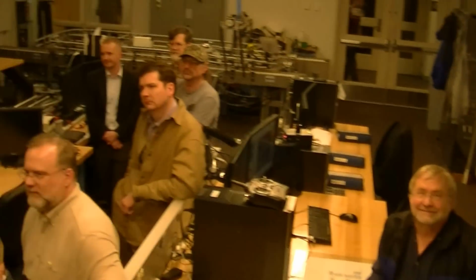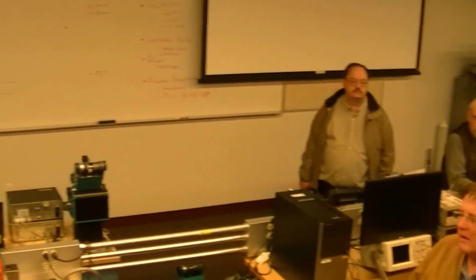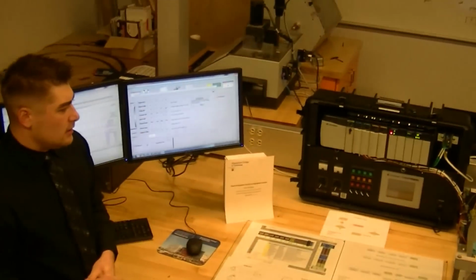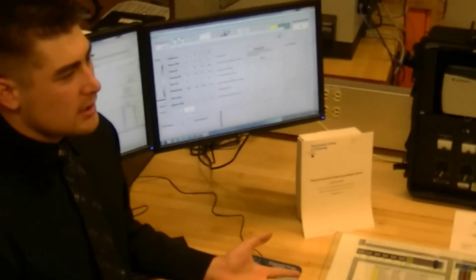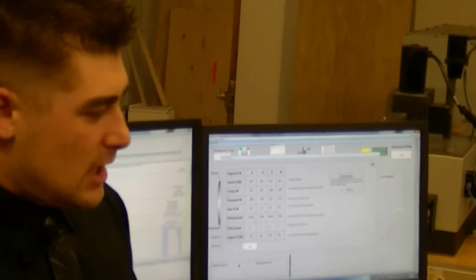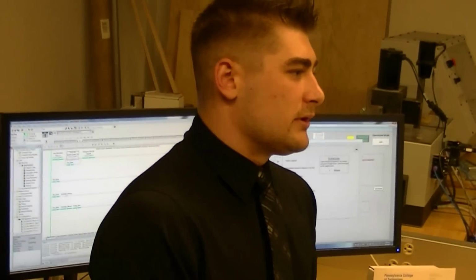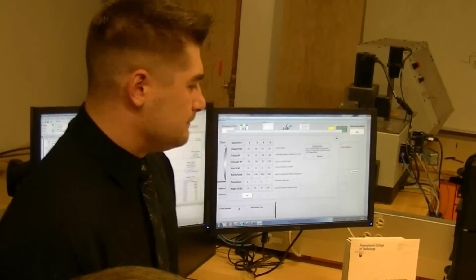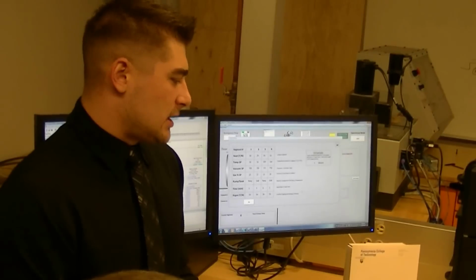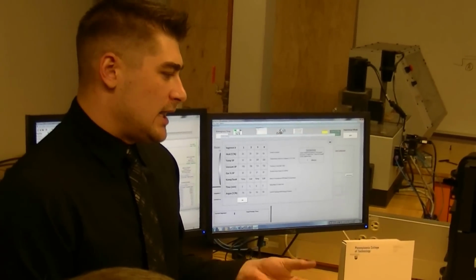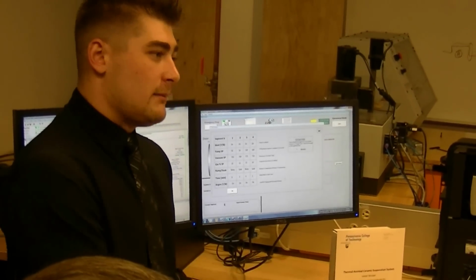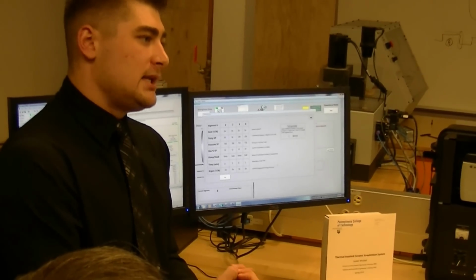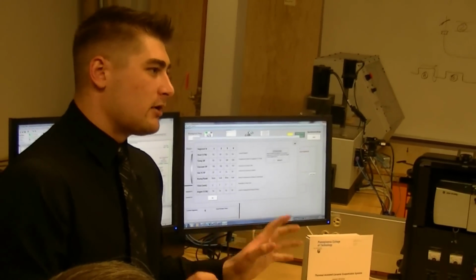Yeah, I used to work for Kimber. They make handguns, rifles, and shotguns. They're famous for their 1911s, and they use this in the metal injection and plastic field. Basically, in a process called debinding and sintering, instead of using ceramic, they use a compressed mold of metal. For example, hammers for guns, safeties, barrel clips, all of that is made by a molding press, and after it comes out of the molding press, there's still a binding agent in there, a wax that holds the powdered metal together.